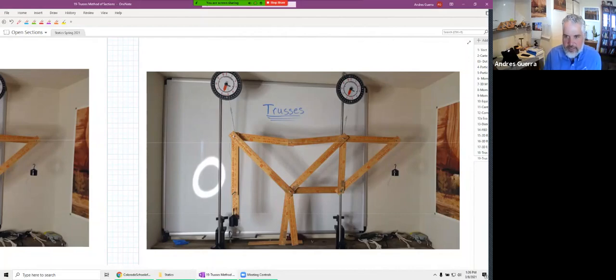Again, it doesn't look very tied together. This joint right here is sagging down a little bit. But we're still holding load, aren't we? We've still got the load there, and we've still got the load there. So we didn't really need those to support the load. For overall stability, yes. Or for a different loading case, yes, we could absolutely need those 0 force members. Any questions?